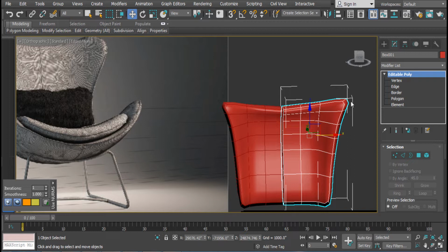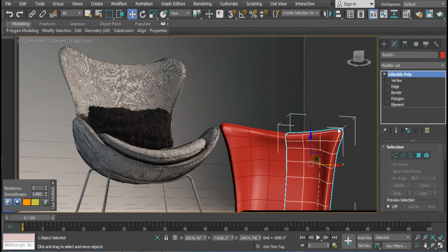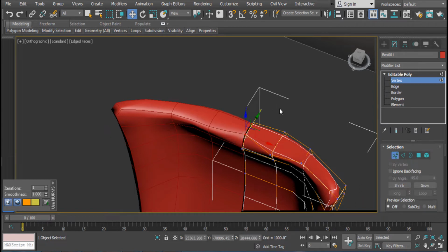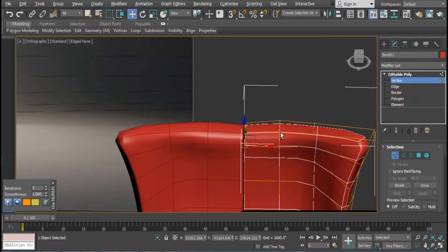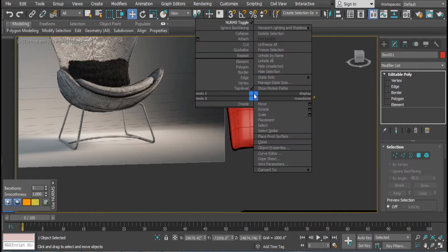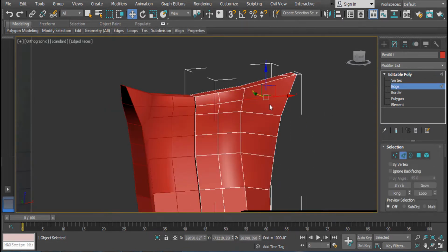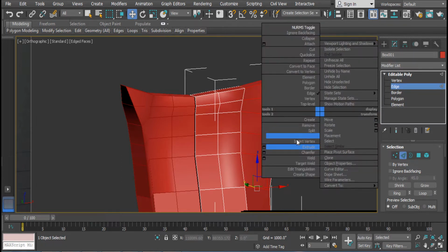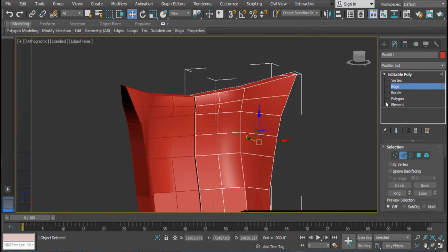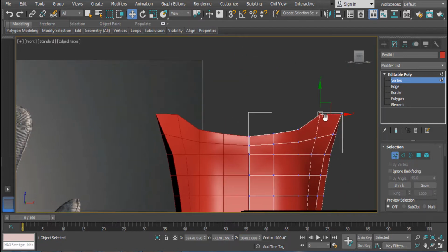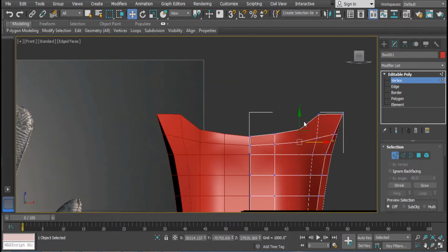On that I showed some pillows and creating some sharp edges in between, how to make the smooth shape in the edges, and how to make the shapes when you're doing changes in polygon modeling, then making a smooth shape with the NURMS toggle. I explained and showed that in 3ds Max 2019 software.